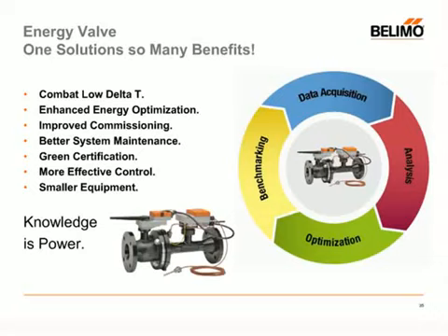You can say, all right, I'm willing to take a 5% reduction in energy. What's that actually costing me? And then you can say, well, it's time to do some preventative maintenance. So you can more effectively schedule preventative maintenance on your air handlers. One of the LEED requirements, if your buildings are LEED certified, to maintain your certification, you actually have to do annual recommissioning. This tool does it for you. All the data is sitting in that 13-month data acquisition system.